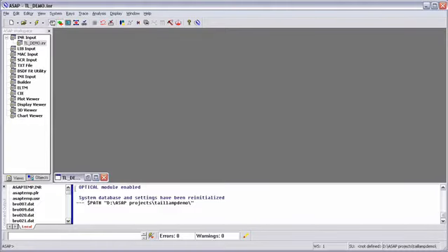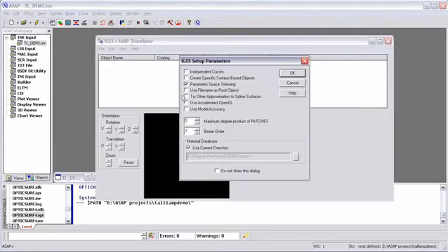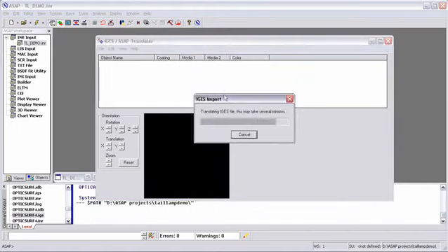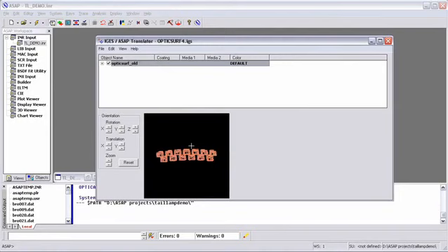Now that we've got an optical surface, we can go into ASAP and convert it into geometry that can be used to simulate the part. If you recall, we saved our file out of Rhino and called it OpticSurf4. I'm going to double click this, and this brings up the IGES translator. We can accept the defaults here, and you can see that we've got our optical surface.